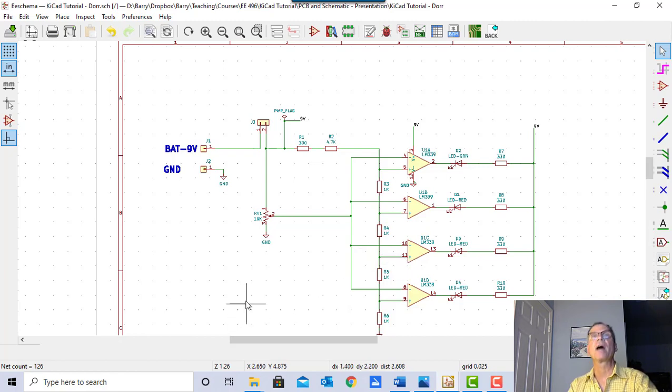So let's fix that. How do we want to do it? We could just tack a power flag on any of these grounds, but that won't look as nice as if we just do it as its own little power flag. And look at our schematic. It's kind of lonely down here anyway. I'm going to put my power flag and ground over here because I don't want it to compete visually with this, but I do want it to sit by itself.